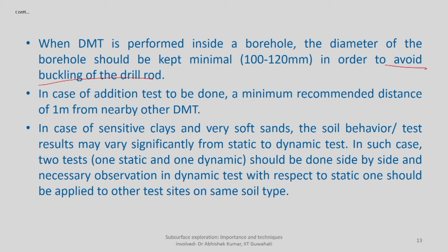In case of sensitive clays and very soft sand, the soil behavior results may vary significantly from static to dynamic tests. So in such cases, two tests, one static and one dynamic, should be done side by side, and the necessary observation in the dynamic test with respect to the static test should be applied, so that the two sites have the same soil type.